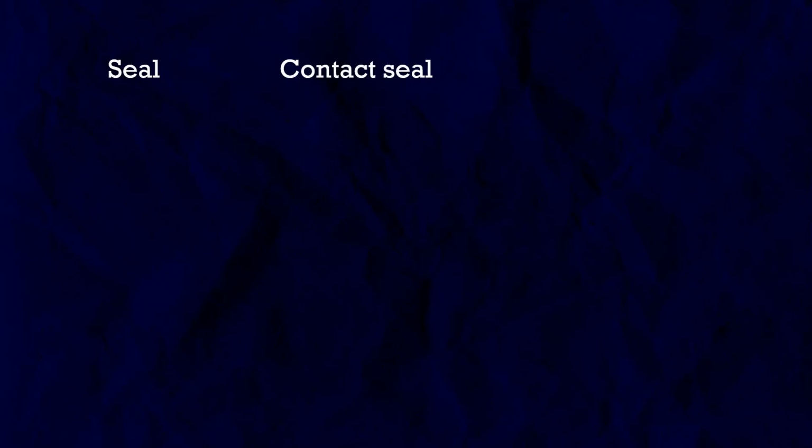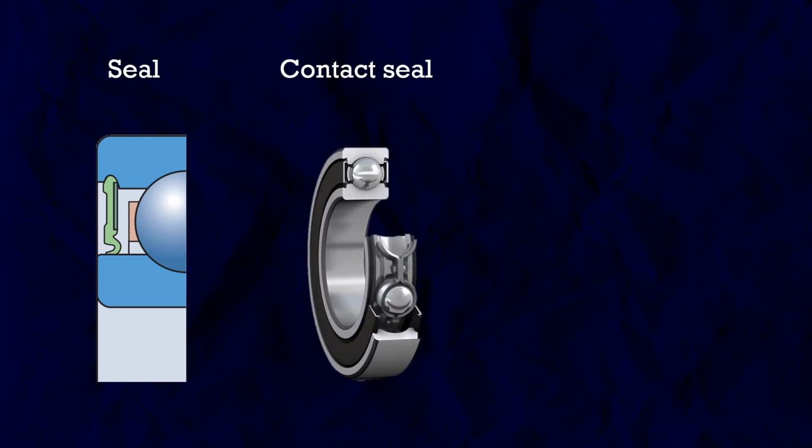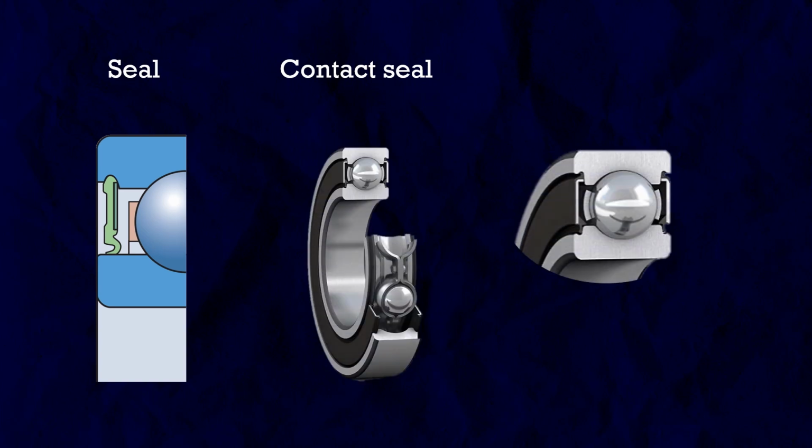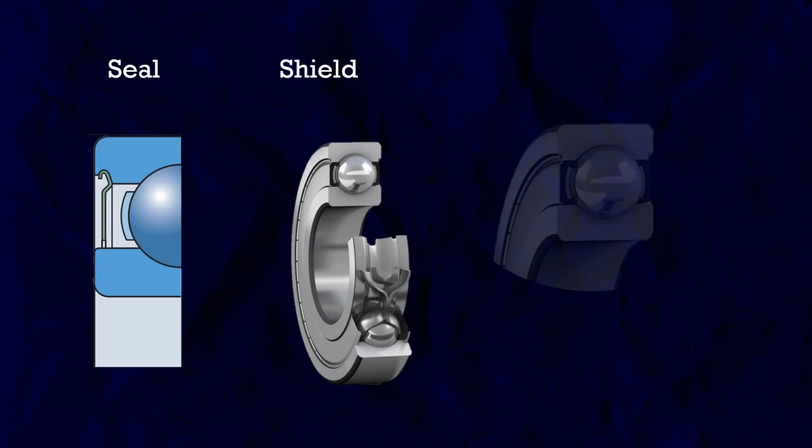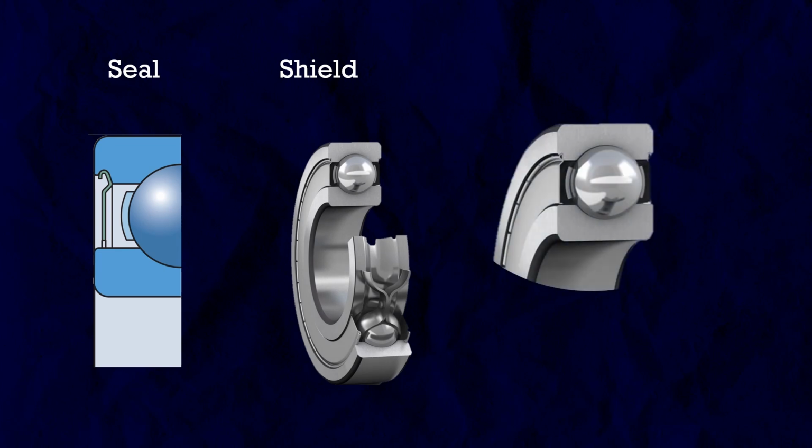And there are mainly two types of seal. The first one is the completely sealed, contact seal, where we need complete resistance from water and liquid. But the problem is, since there is positive contact, friction will be high and we cannot use it for high speed. So for high speed, we can use a shielded seal, how to pronounce it, but you can read it.